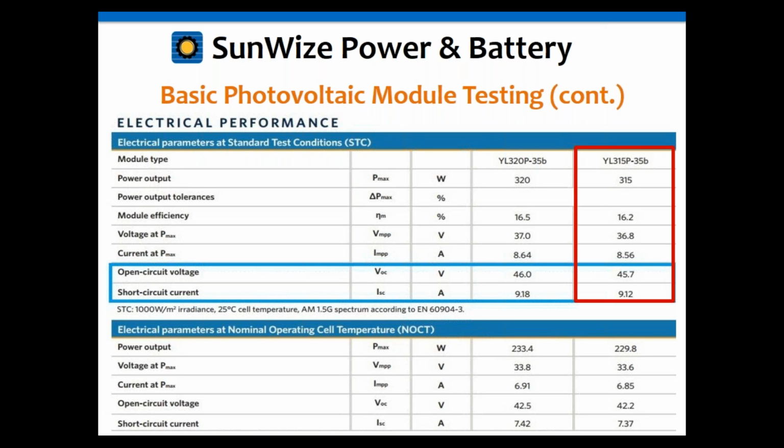And we're looking at just basic troubleshooting at this point. We're not actually confirming whether the module meets its actual factory rating anymore. We're just trying to figure out whether it's functioning or not. So we're just going to look at the basic numbers again. So for discussion purposes, NOCT or ISC values are acceptable to use.